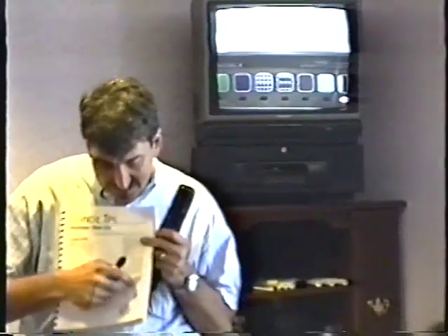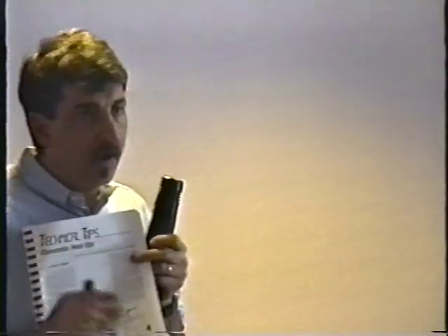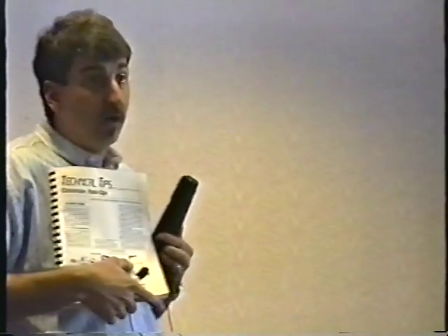It's the same video ground as pin 4 on the 6-pin connector, and you can put your video ground on either pin. It makes absolutely no difference whatsoever. They're connected internally inside the monitor anyway. You can use either one.